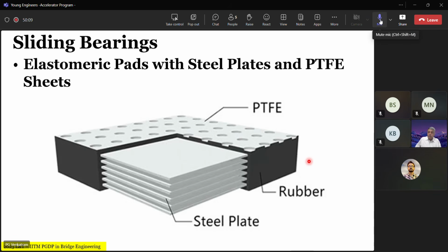Now, sometimes it depends upon the intensity. Please remember one thing. When do you need the steel core to yield? You need it in a very high earthquake. Then you have much higher energy absorption, therefore much higher energy dissipation.